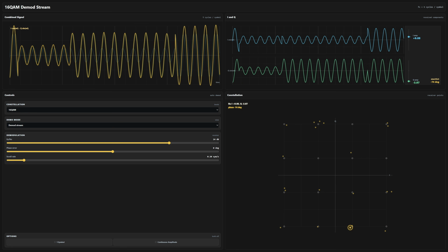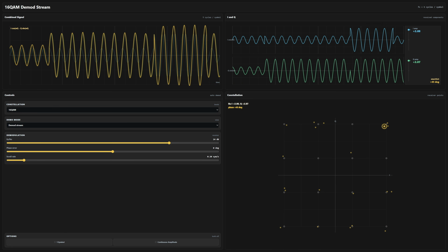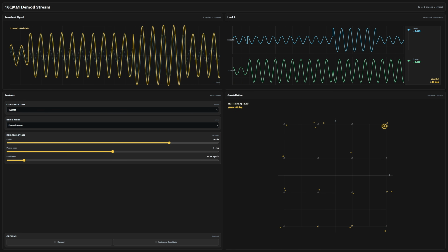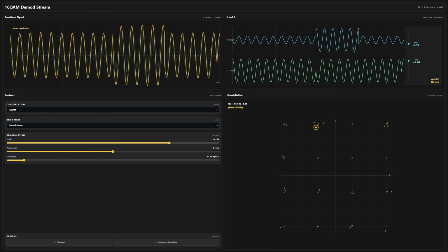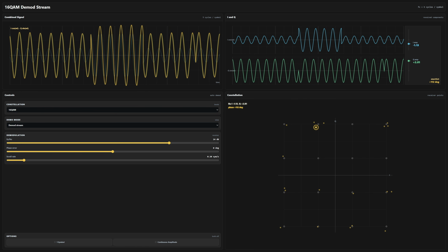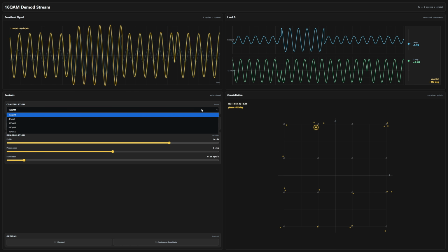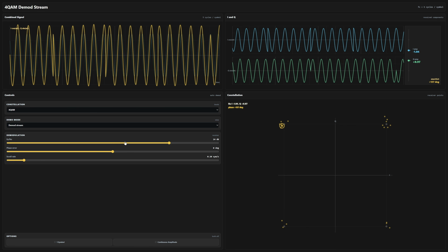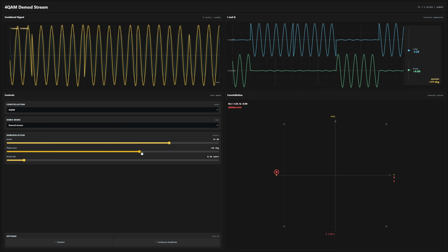Likewise, when an incoming signal is demodulated, it will be mixed with both in-phase and quadrature carrier waves to recover the carrier phase and amplitude. This is called coherent detection. For RF demodulation, the local oscillator needs to be in sync with the transmitter's carrier wave.